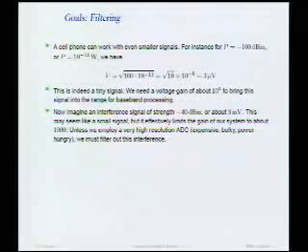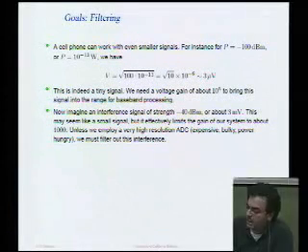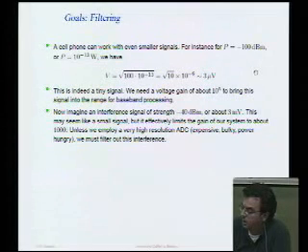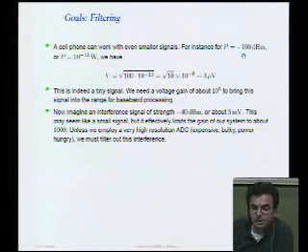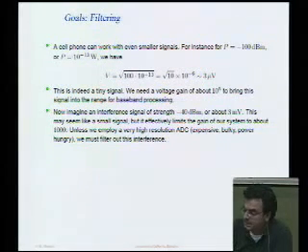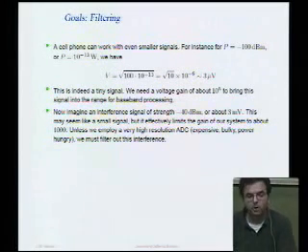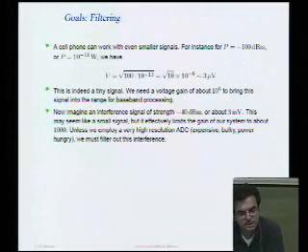But what about a cellular phone? At the same time as you're receiving that wireless LAN data, you're also receiving a cellular telephone call, and the signal there is minus 100 dBm, and the cell phone has to work. How small is that? That's 10 to the minus 13 watts. Using the same formula, translated into a voltage, that's just 3 microvolts. That's a really small voltage. To gain some intuition about how small that is, go in the lab and look on an oscilloscope.